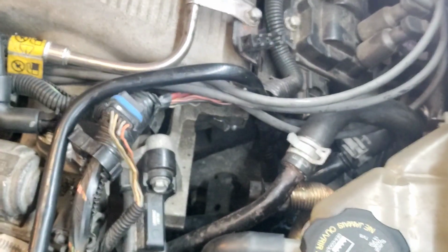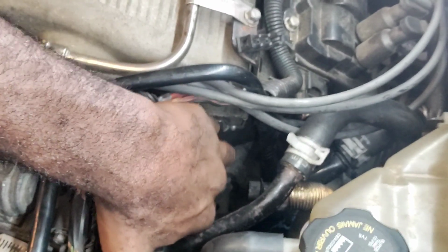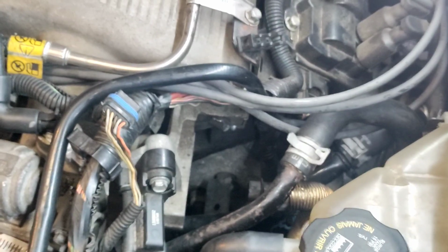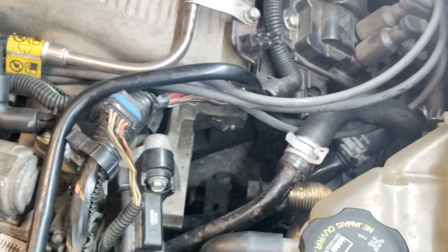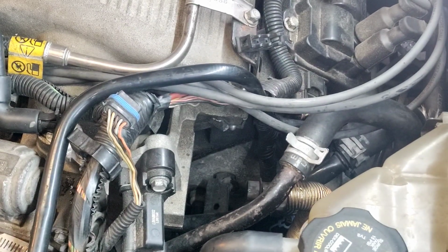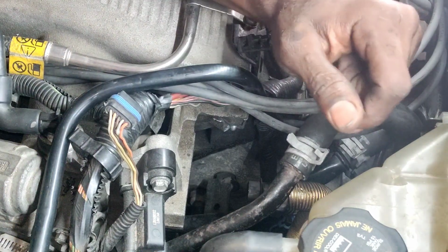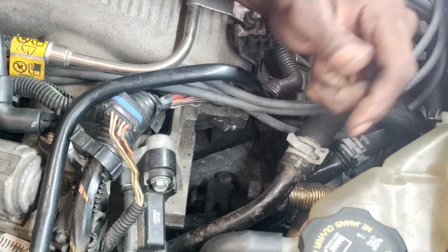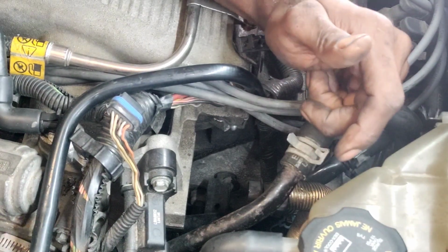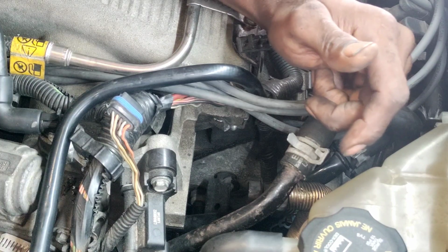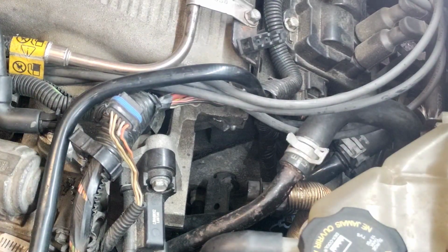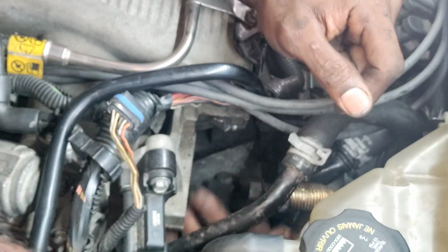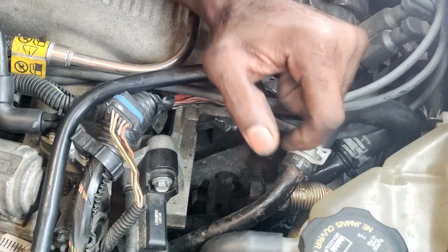So there's no vacuum. This is weak vacuum. Technically the car shouldn't be running because I created a vacuum leak. So there's an obstruction. I mean, let's prove myself correct. Let me put this cap back on here. So I'm going to take a pick, get inside of there, and clean what I can in there. It should be a straight shot.